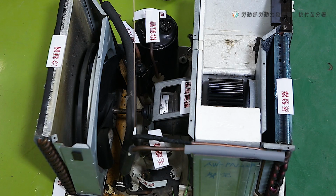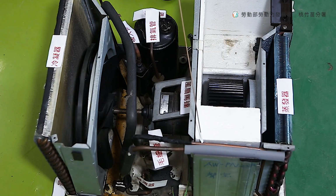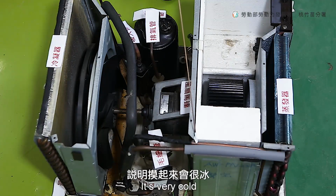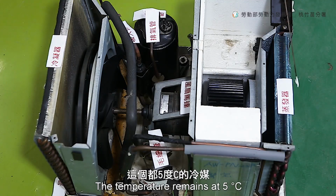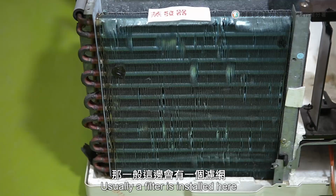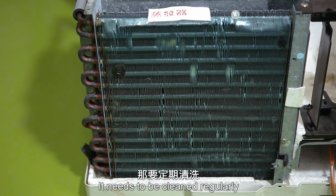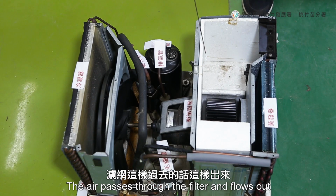After decompressing, the refrigerant's volume increases. The temperature of refrigerants here is 5 degrees. It's very cold, and the refrigerants pass through the copper pipeline. The temperature remains at 5 degrees. Refrigerants flow in here, and the indoor air flows in from here. Usually a filter is installed here. It needs to be cleaned regularly. The air passes through the filter and flows out.